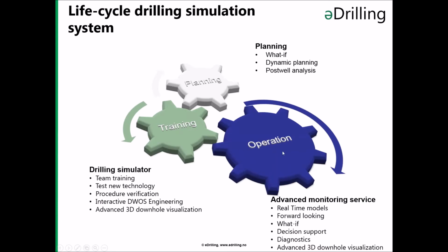To summarize, what we now have is a full life cycle drilling simulation system consisting of planning models. You can do what-if evaluations, you can do dynamic planning of hydraulics and so on, well control, torque and drag. Then we can take the same wellbore over to a training environment where you can do training of your drilling teams.